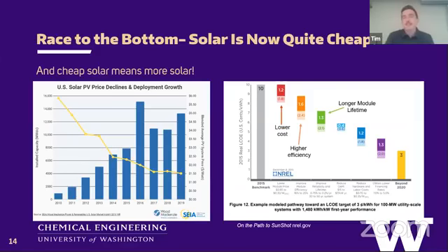Yeah, that's a really interesting question, and we'll talk about this in a little bit. I'm working in a particularly unreliable PV system material. So a lot of times they die due to moisture ingress: water or humidity breaking through this protective plastic layer that we put over every solar cell to try to protect it from water.